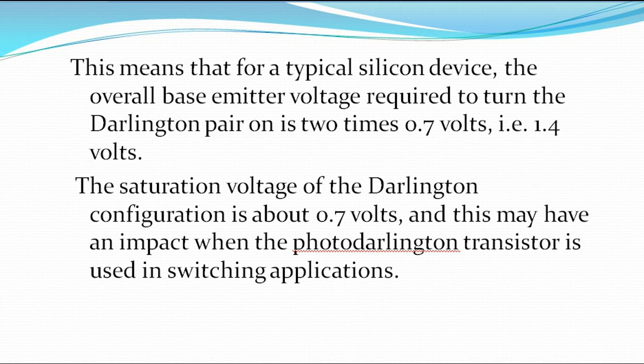The saturation voltage of this Darlington configuration is about 0.7 volts, and this may have an impact when the photo-Darlington transistor is used in switching applications.